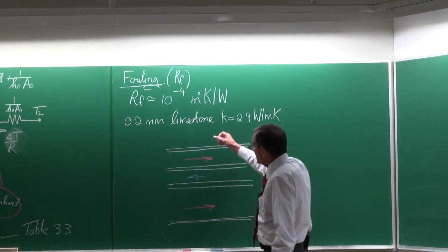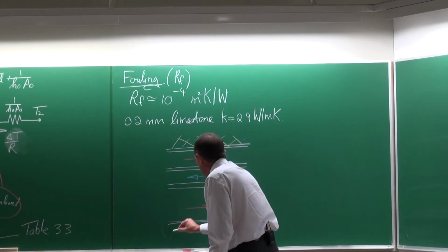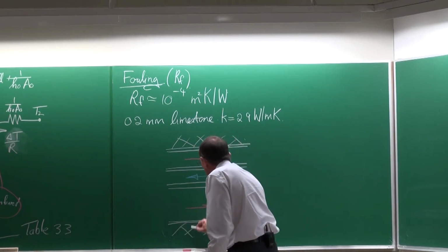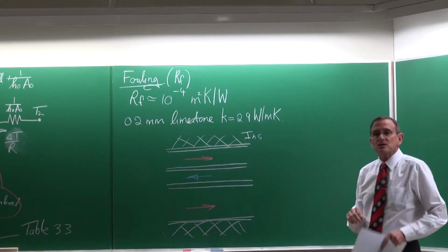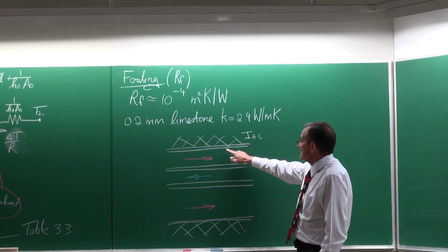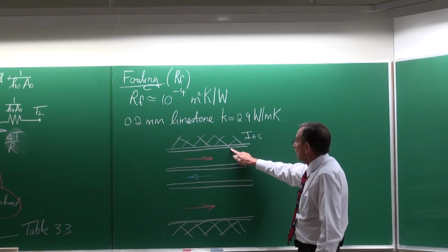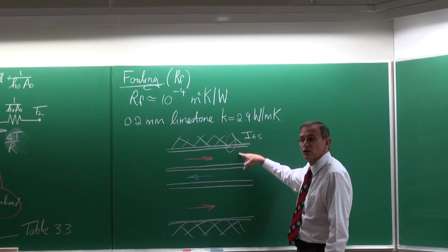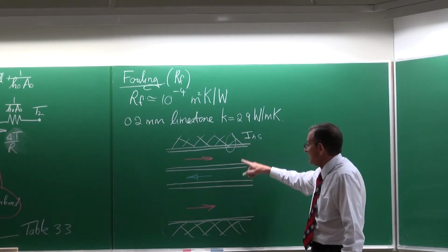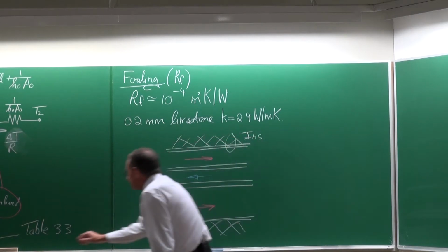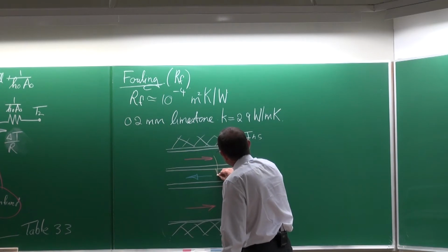In most heat exchangers there will be insulation. You don't want heat transfer to the environment, so there's your insulation material. So it's very important to notice that the scaling or the thermal resistances because of fouling will almost never occur on these surfaces because it's an adiabatic surface. There's no heat transfer. The heat transfer will occur through this surface from the hot side to the cold side in this case.